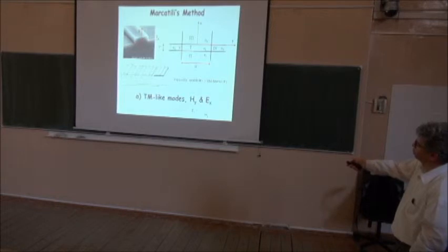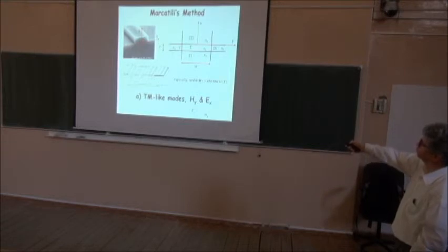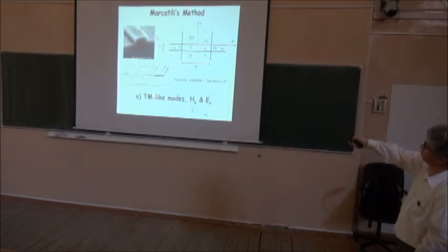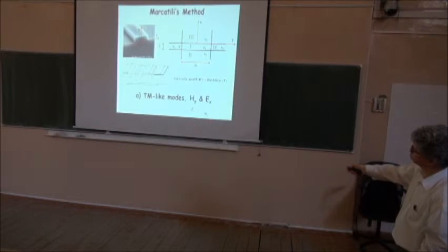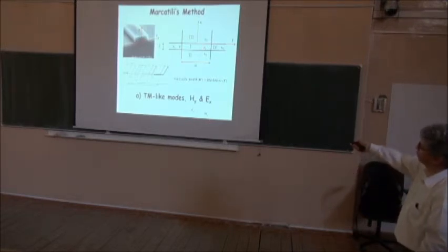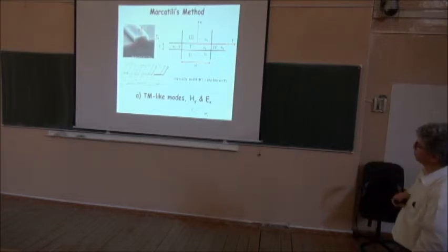I'm going to call this TM-like because I do have some finite confinement here. And I do expect here, in addition to the H being along the Y direction, the E should be along the X direction, its major value there. So I'm expecting solutions that will have this profile in that guided region there.